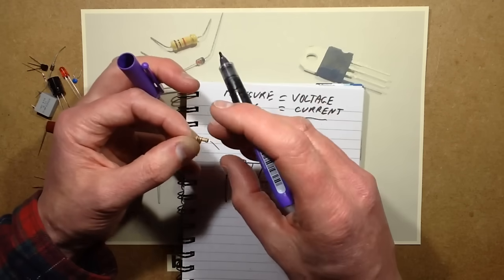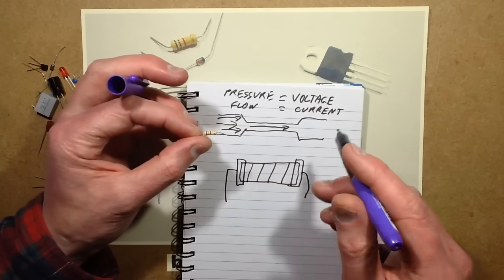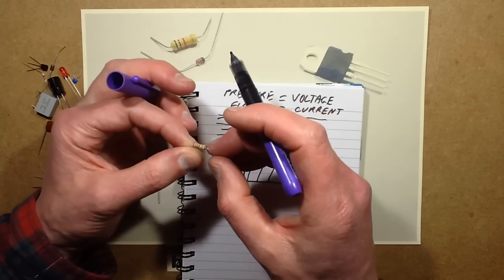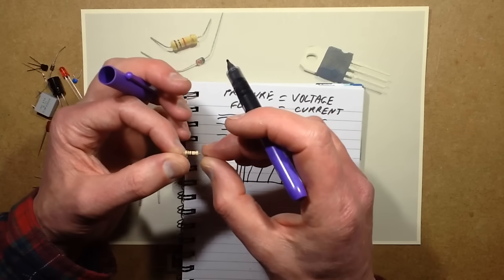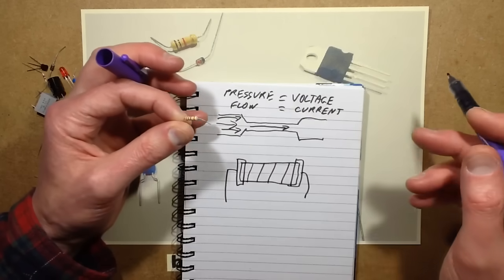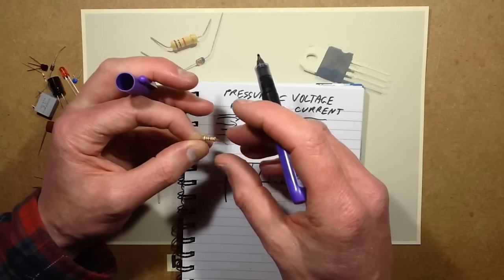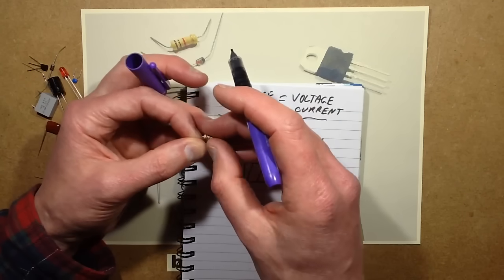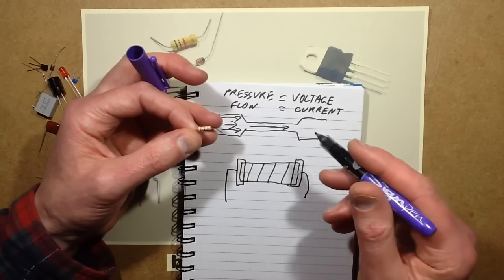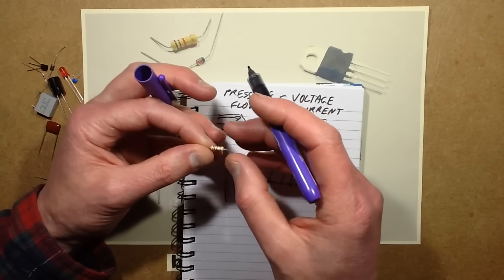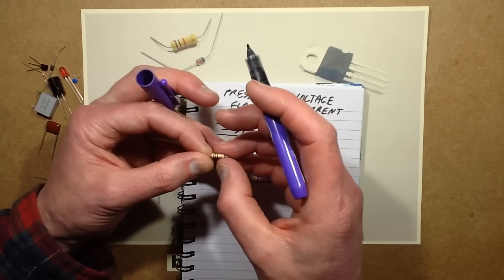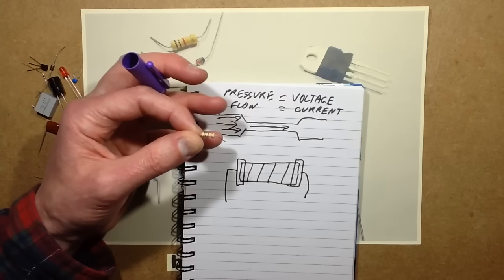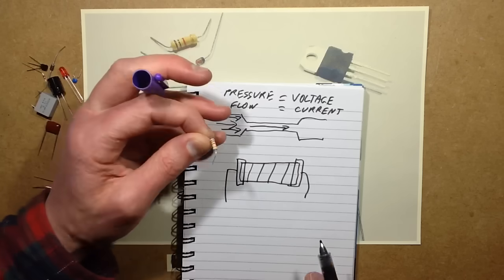And typically with the carbon film resistors, which are my favourite, they're one of the easiest to read, it'll be this sort of beigey coloured, I'm not sure, what would you call that colour? I've never really thought about that. Beige, let's call it beige, it's sort of rich beige. And the metal film resistors, which I don't like, because they're usually blue, and they're really hard to read. The blue colour makes it easy to mix up colours like orange and brown, because they've got such a dark background. But I'll go into those colours afterwards.